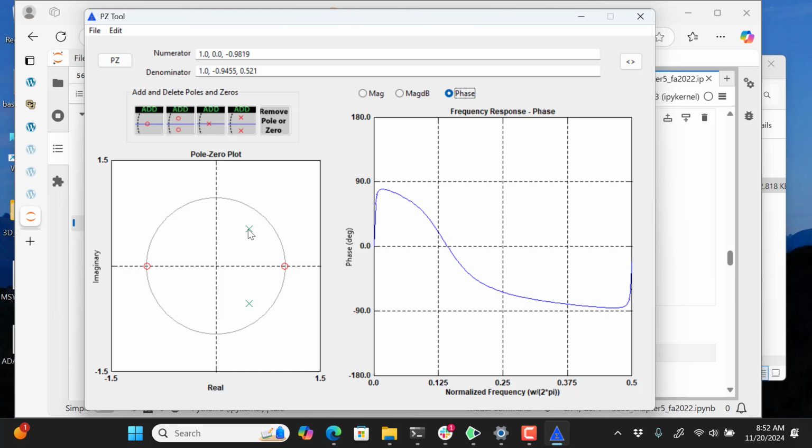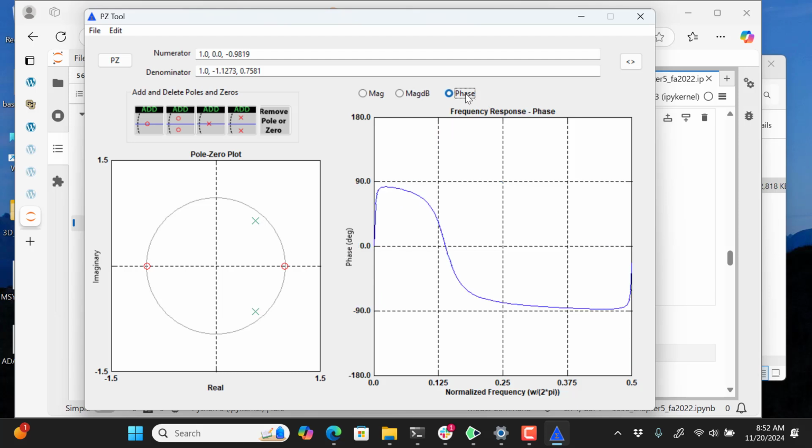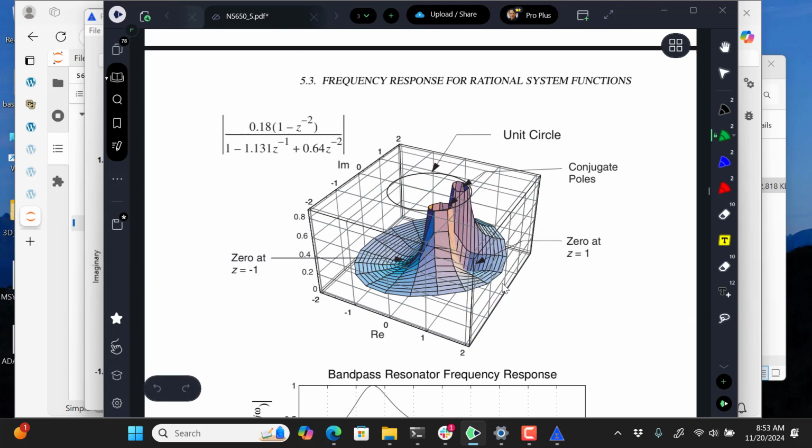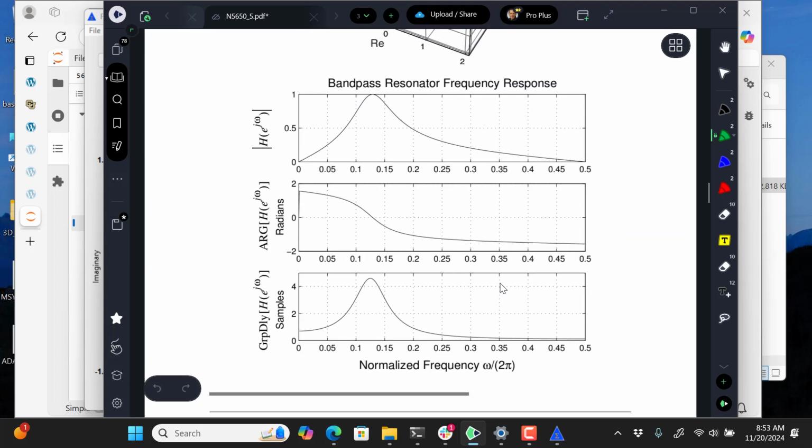The group delay won't be too much, but as we move this in tighter to get the tighter bandpass peak, the phase makes a more rapid transition, and it's going to create a bigger blob at the point where the peak is, and that's depicted right here from the analysis.